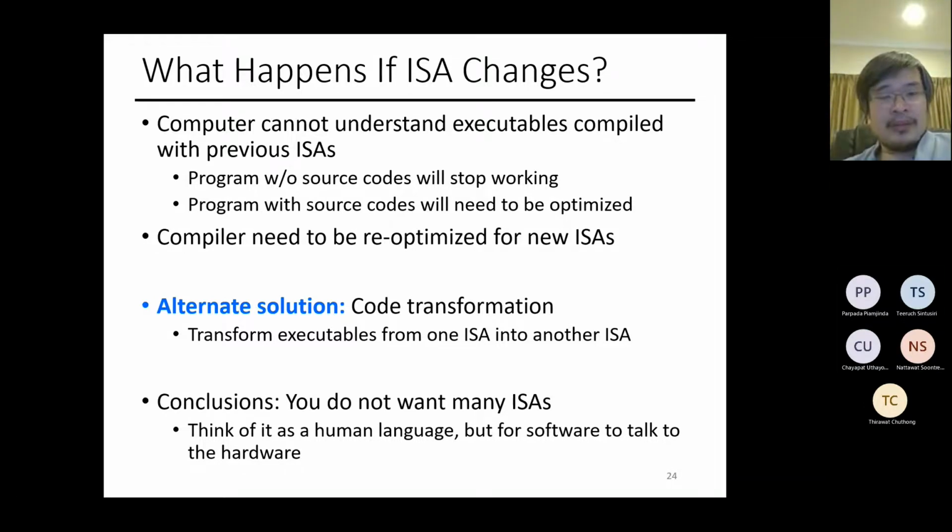All right, so basically, in conclusion, similar to human language, it's actually convenient to have one language. But again, there's a trade-off in everything, right? Certain ISAs might give you more registers. Certain ISAs might give you the ability to do fancy tricks. Certain ISAs are really, really minimal, like RISC-V, and don't give you a lot of instructions to do, but then you can use the transistors for something else in the microarchitecture as well, right? So there are trade-offs that come with each ISA.